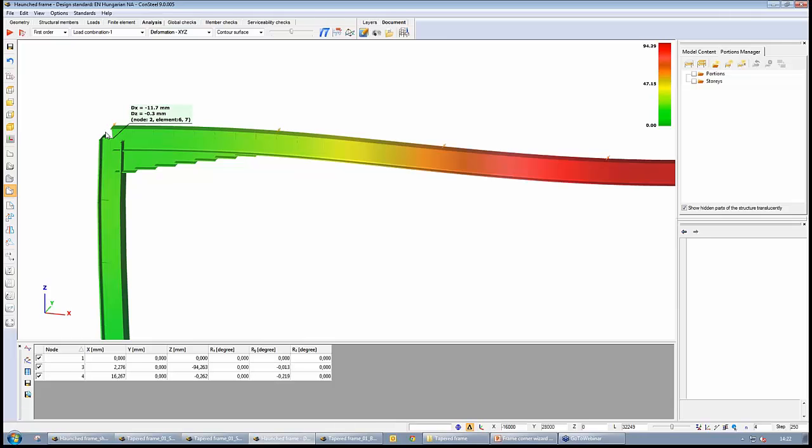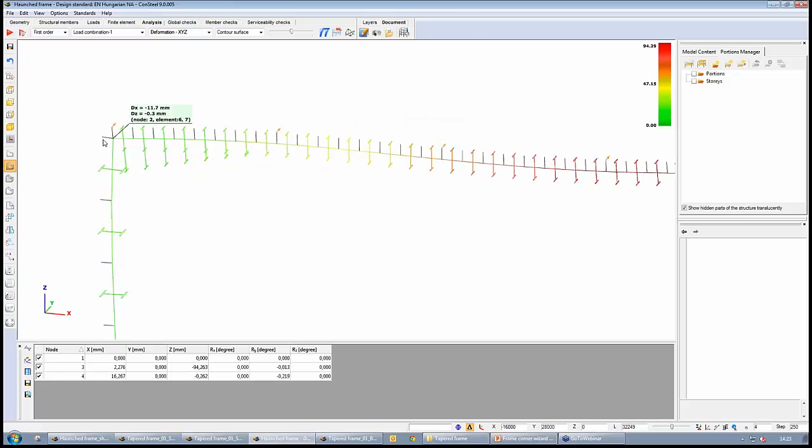And also the lateral torsional buckling, so the stability behavior of these frames, is calculated by considering a continuous connection here at the theoretical node between the two beam elements. So this line and this line.